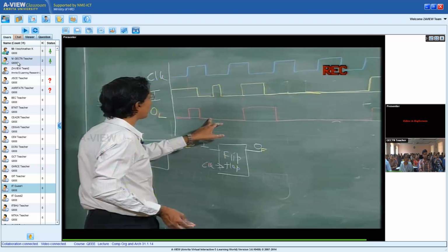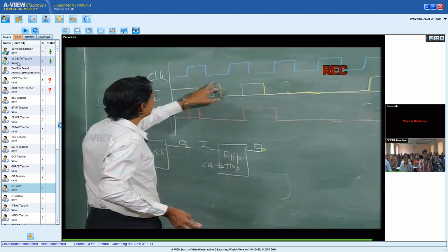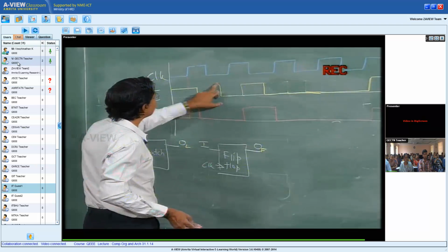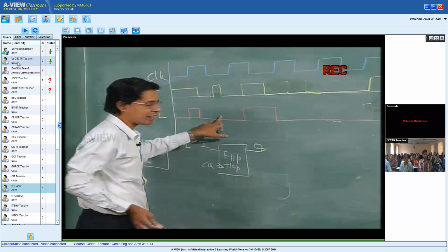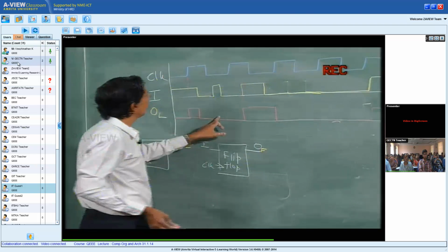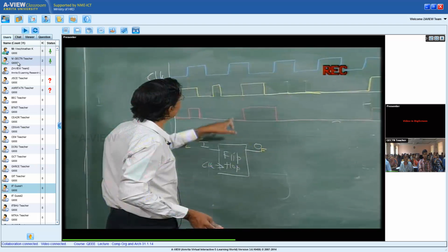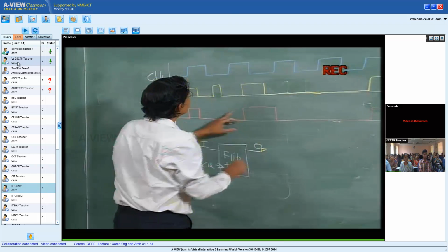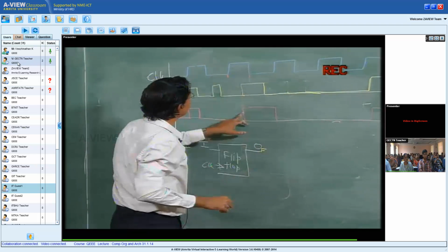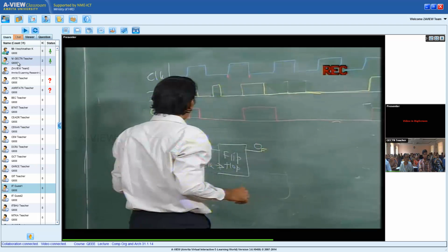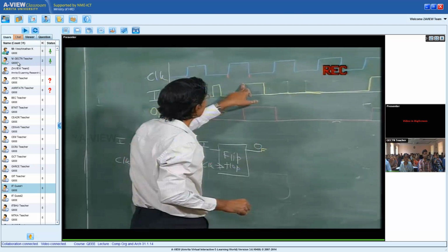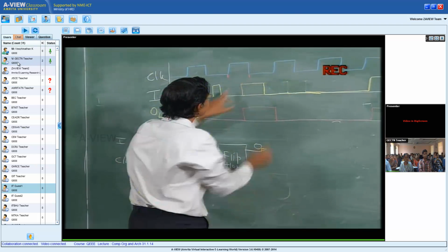So it is at 0, it continues to remain at 0. So in this intermediate period, when the clock is 0, when the input changes, those changes are not reflected in the output of the latch. Now this goes on again when here the clock goes high, between this part and this part, the latch behaves exactly like the input. So the input goes high in the middle, then again it is high here.